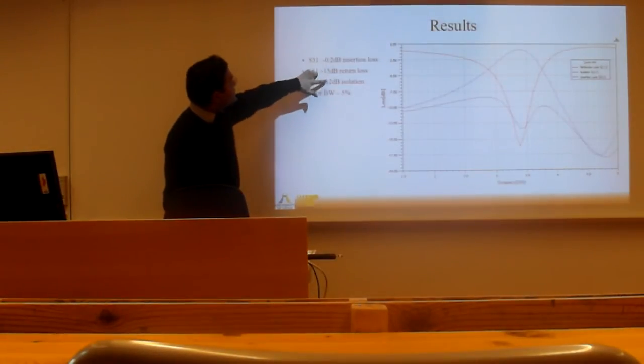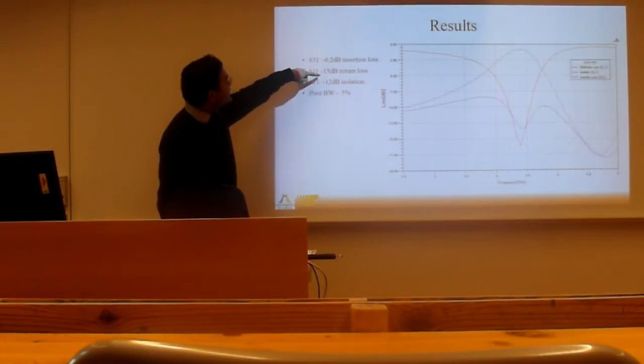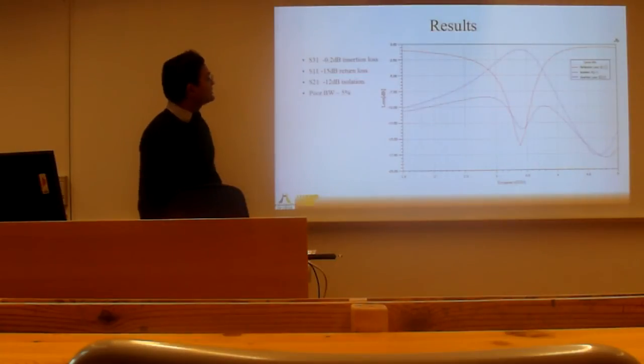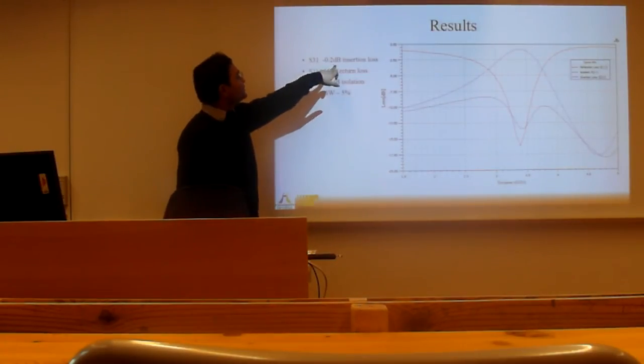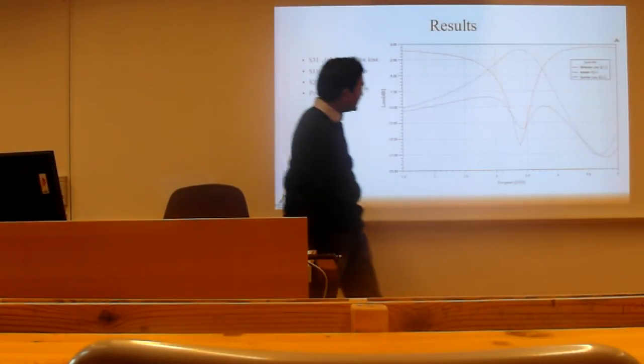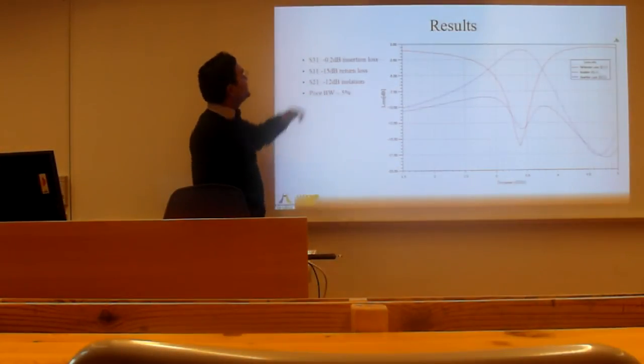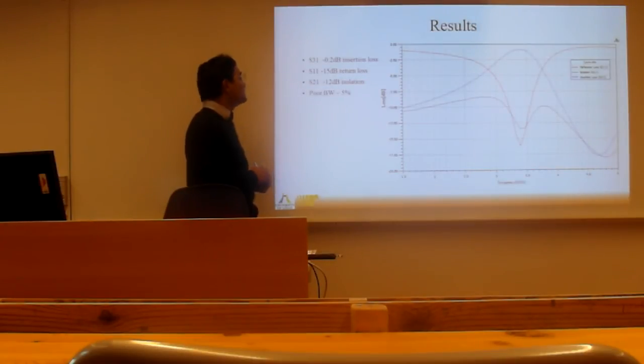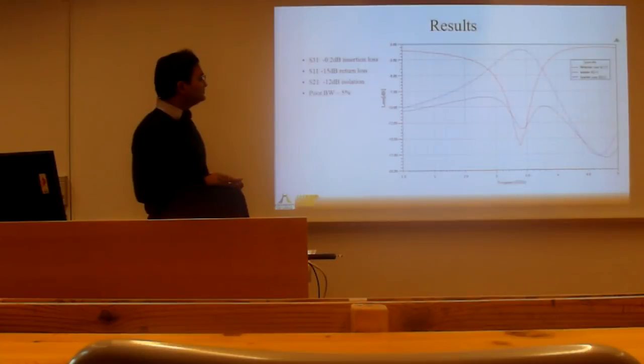These are the levels at the operating frequency: minus 0.2 dB insertion loss at the operating frequency of 3.125 GHz, 15 dB return loss, and 12 dB isolation.